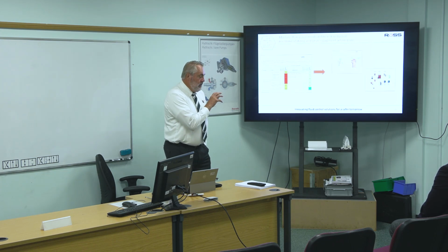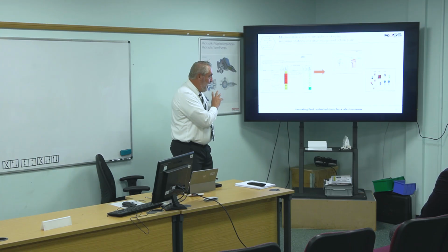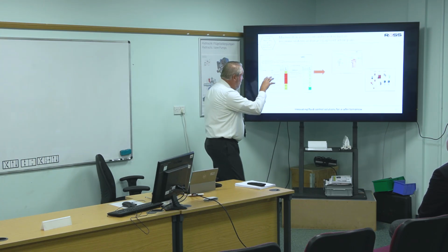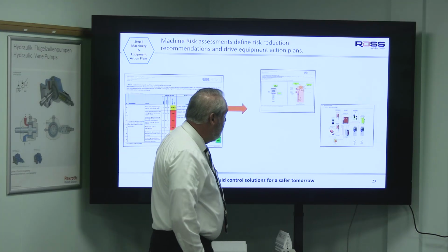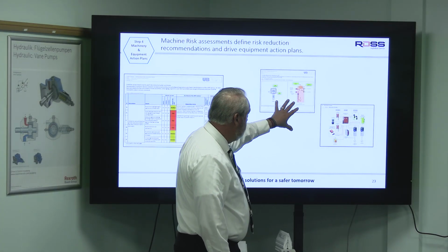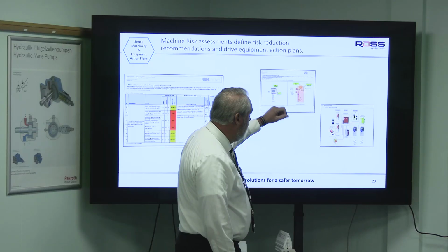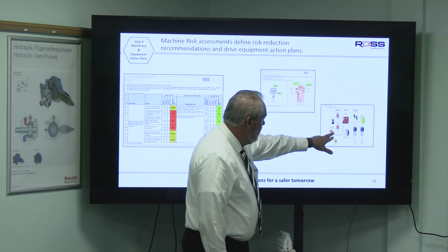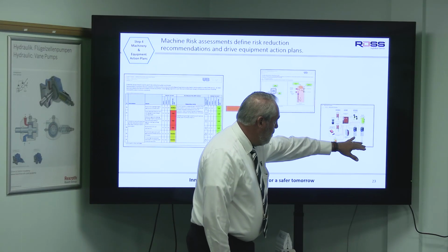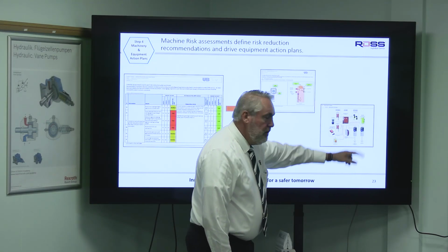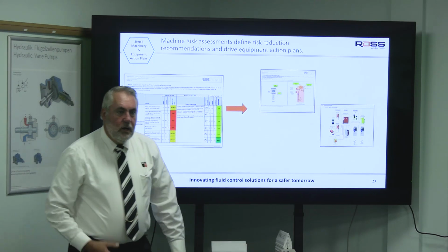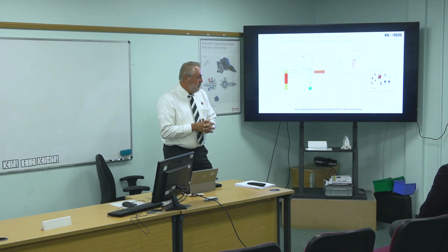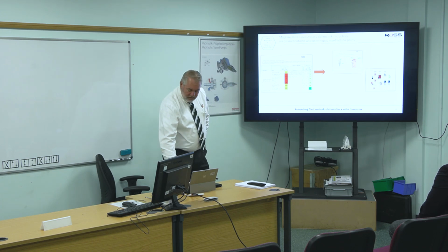And then those risk assessments and those HAZOPs should drive what we call a machine risk reduction plan. And this one is a machine safety risk reduction plan. It showed where we needed to put guarding, where the area scanner was going to be configured to prevent access, and then what we needed to do to control both electrical energy, but also pneumatics and hydraulics. And so this is where your system kind of starts tying together those electrical devices to the output devices.